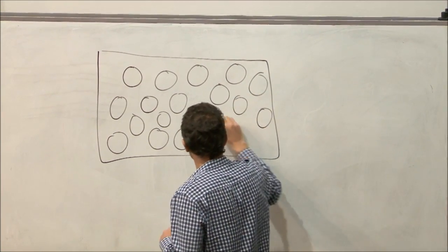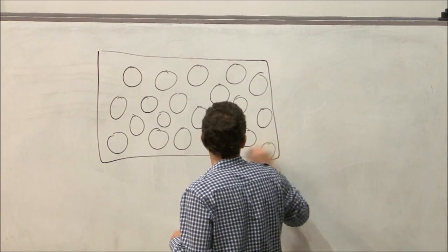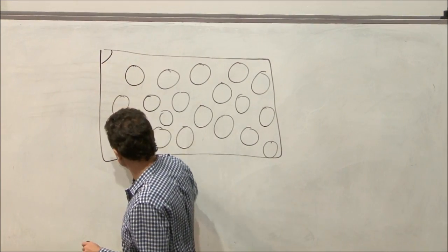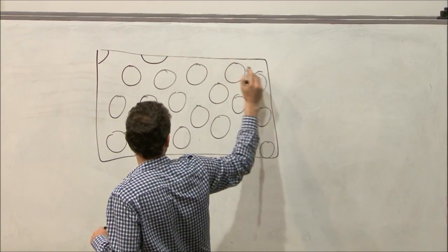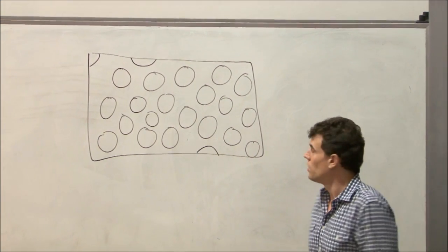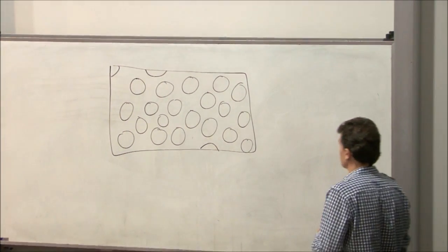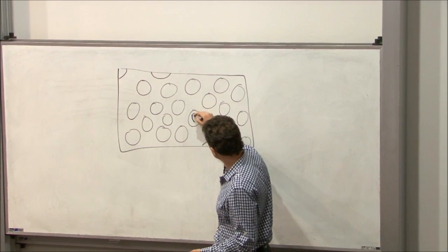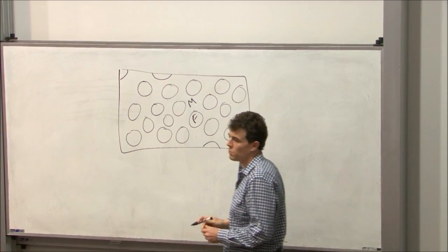Some types of carbon fibres aren't quite circular, but okay. And obviously, depending on where I'm looking in the microscope, I can have fibres hanging over the edge too. Okay, so if I've cut through my specimen and I can see these fibres, obviously the circular bits are the fibres and the rest of it's matrix around.